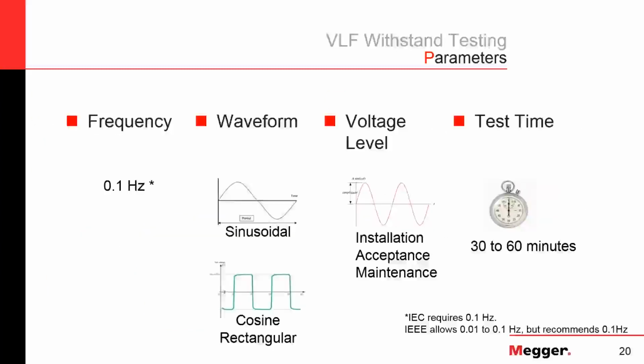And this, of course, increases the reliability of the system. So the parameters for VLF testing: frequency is 0.1 hertz. We can use sinusoidal or cosine rectangular waveforms. Voltage level would be acceptance testing, installation testing, or maintenance testing, based on where we are in the lifetime of the cable. And the test time is 30 to 60 minutes by IEEE.